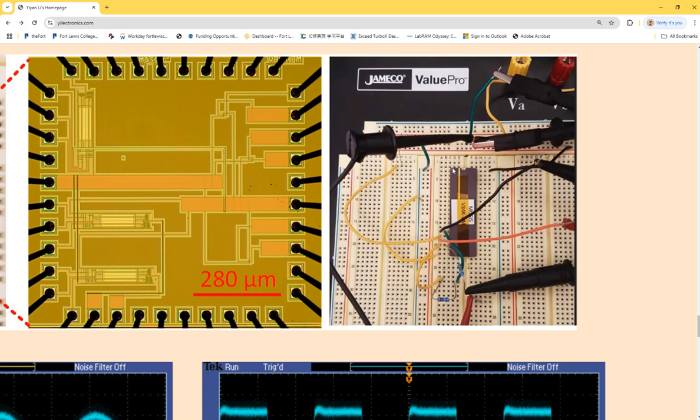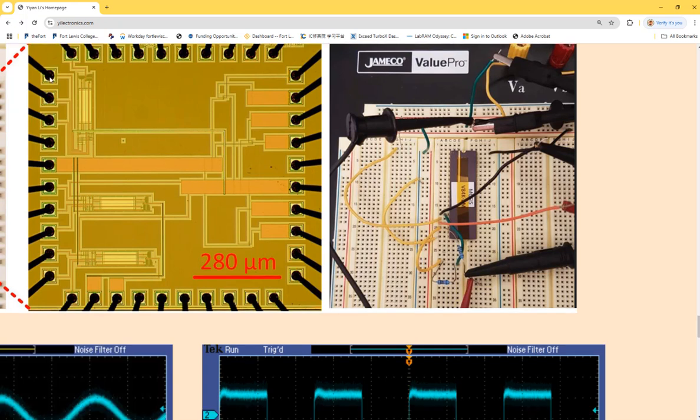So these are the pins of the chip, and that's a little cover. And I showed you guys on the first day, there's a little silicon die in the middle, which is a chip. This chip's dimension is about 1.5 millimeter by 1.5 millimeter. And these bonding wires are bonded to smaller pads in the middle, underneath this cover. You do the wire bonding inside this area, and these pads inside, you cannot see because they're covered by this little lid.